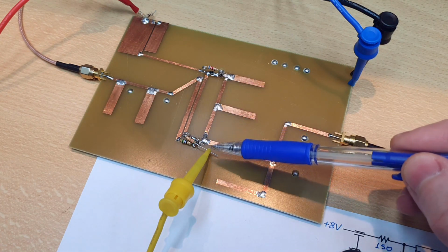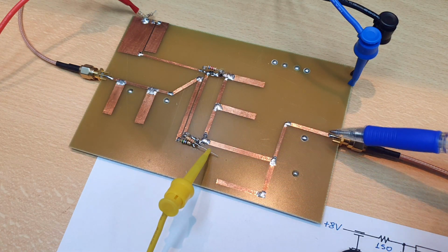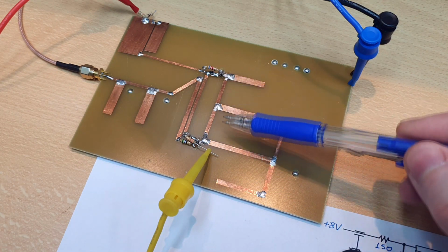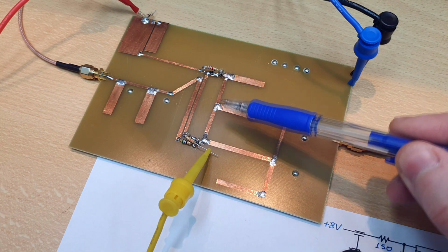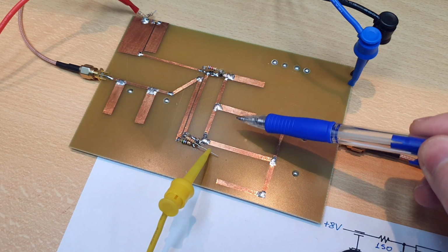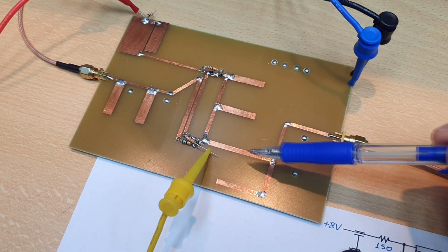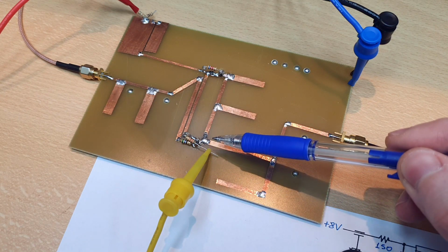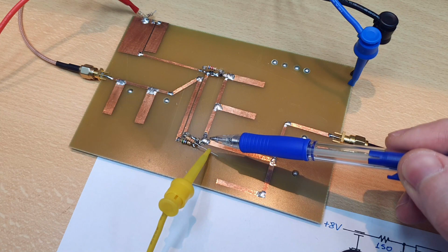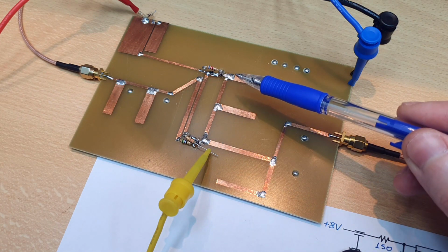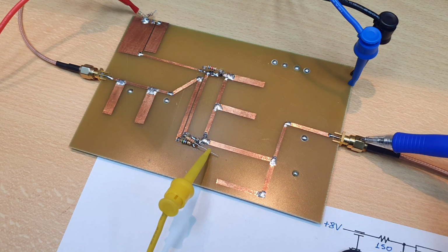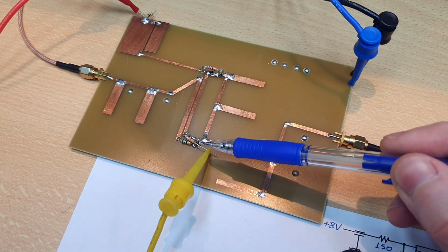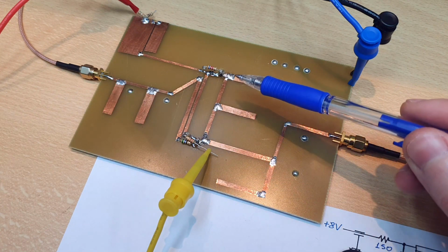So we need to prevent the 1.6 GHz input signal from going to the amplifier. So we have this trap here that works at 1.6 GHz. The two networks are composing a duplexer where you have frequency multiplexing. So here at the output node of the mixer, the 800 MHz signal can go in that direction and can't leave by the input port. And the 1.6 GHz signal can arrive at the mixer and can't go to the amplifier.